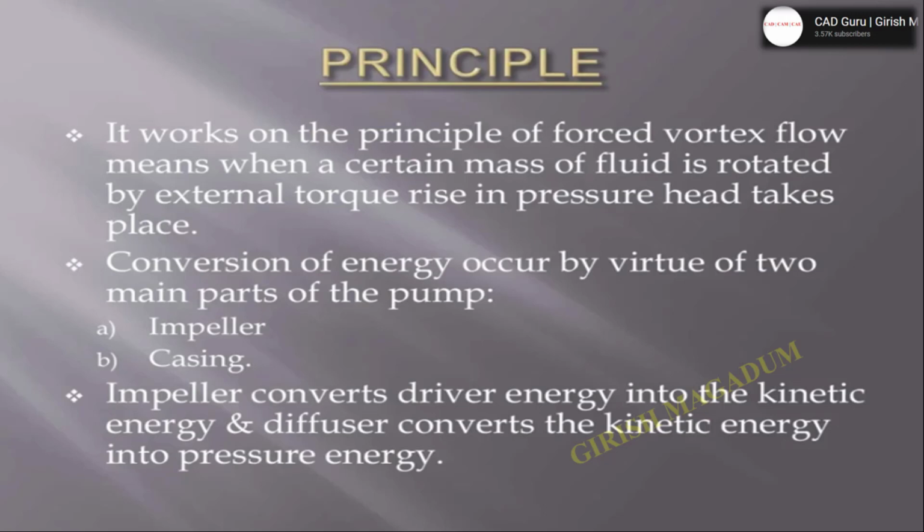This conversion of energy occurs by virtue of two parts of the pump: the impeller and the casing. The impeller is the rotating region, which converts the driver energy into kinetic energy. And the diffuser, the casing stators, will convert the kinetic energy into pressure energy, vice versa. By this, the multi-stage pump is able to produce more pressure head and more flow accordingly.